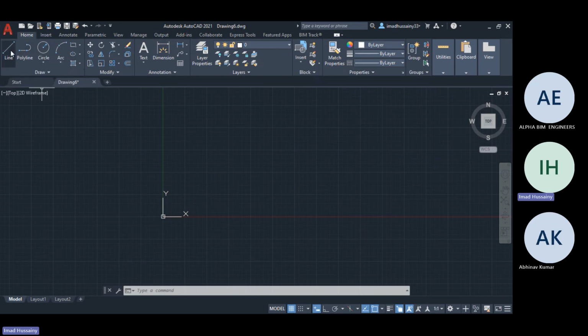That is the line command. Without line, you cannot draw anything. So first let us draw a line. You know Cartesian coordinates. It is nothing but your graph, like 0, comma 0. Once you give 10, comma 10, it will take that particular point in the plotting. So in 2D, you specify points on the X and Y plane, and based on that, you can draw a line. In 3D, we will give X, Y, and Z, but in 2D, we require only X, Y under our work plane.